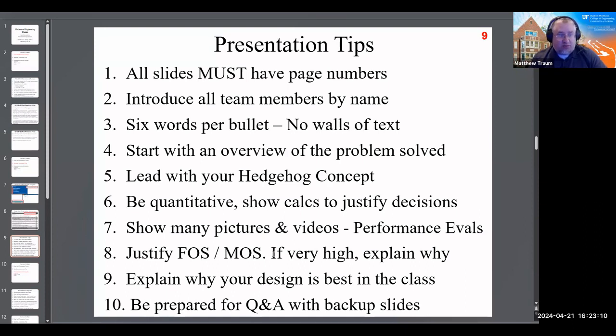There are situations where you get high factors of safety. One great example is if you are buying commercial off-the-shelf parts that have all of the features and all the functions that you want, but they're just a little beefier than what you need, and would end up being much less expensive to acquire than making that part yourself. That's a situation where you could end up with a part that has a really high factor of safety, but you pick it anyway because it's the best option to keep the cost down.